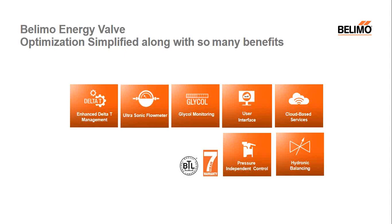At its core, the Energy Valve is a pressure independent control valve. So it eliminates additional balancing valves because it's now performing that hydronic balancing, and it eliminates additional circuit setters. So it really is a lot of things built into one compact package.